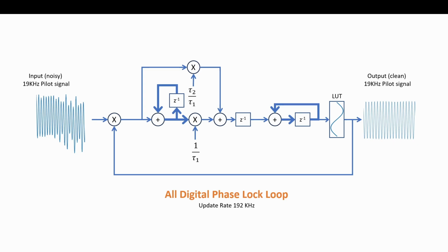That lookup table is just giving you the trigonometric operation: tell me the sine of that phase word. The faster we count, the faster the sine wave is going to go, and it keeps cycling on itself, so we get a continuous sine. If I count by 2, it's going to go twice as fast. If I put a 3 here, it'll go 3 times as fast. So it's a numerically controlled oscillator. Make sense?